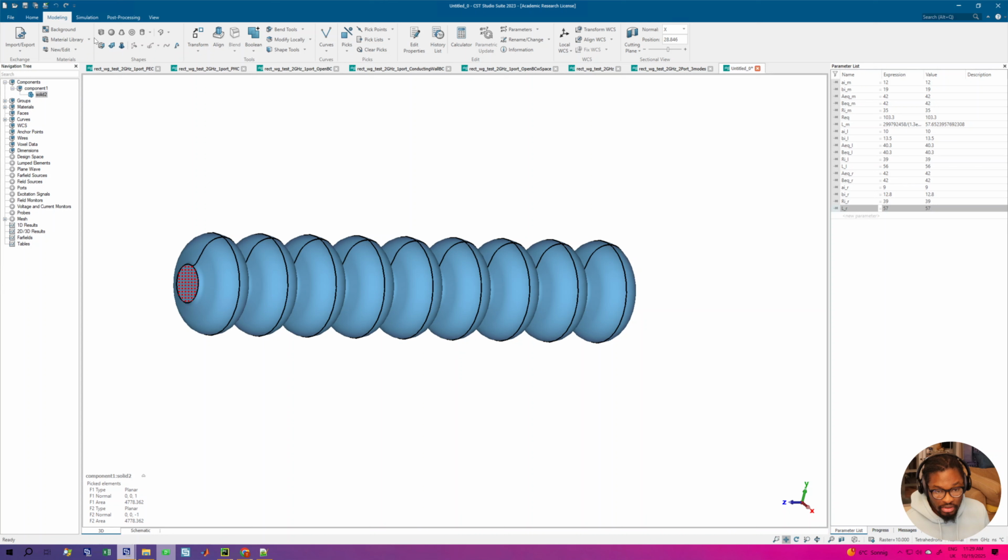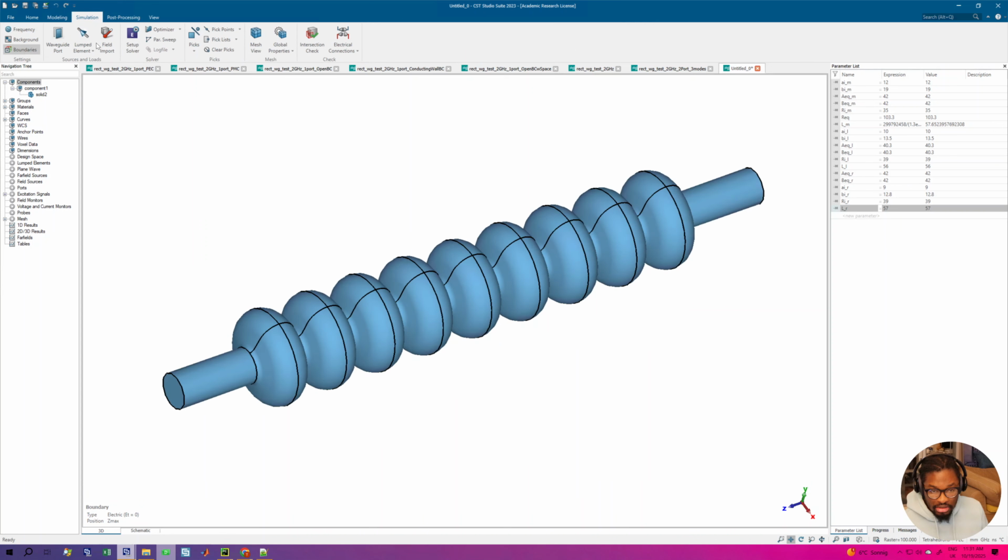Apply everything. I'm not going to use waveguide ports. I'm just going to leave it at PEC. At a good enough distance, the boundary condition is not supposed to affect any of your modes, your fundamental modes, because they're localized in the cavity. But for propagating modes that propagate out through the beam pipe, you'd have to be careful. Yes, I think that's that.